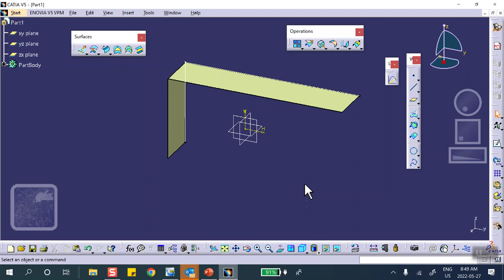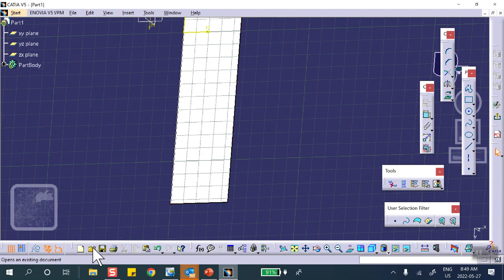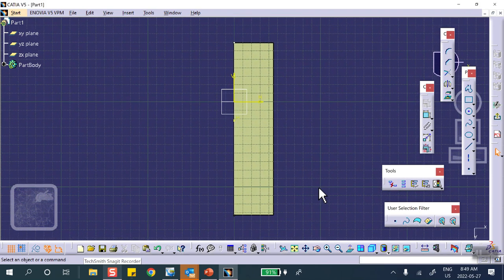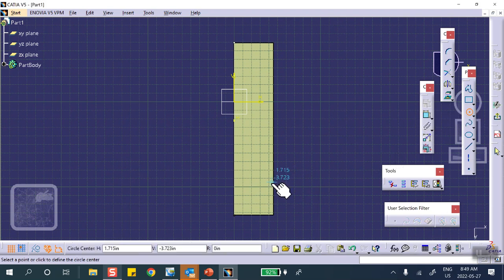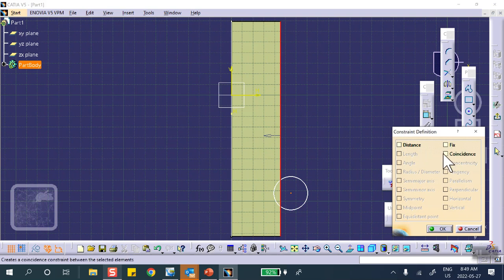So this is one way that it works in surfaces. On that top face, I will sketch. So the hole, I want to make it down here. Okay. So I'm going to make a circle somewhere there. But I want this center to be on that line. We know how to do that. So this point controls that line. Line, coincidence, or dimension and dimension 0, etc. Exit.